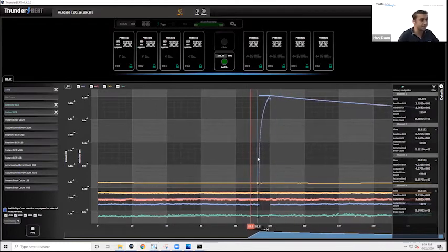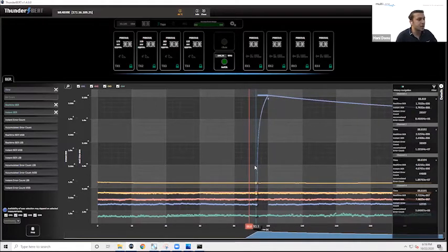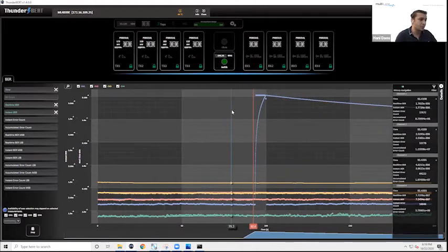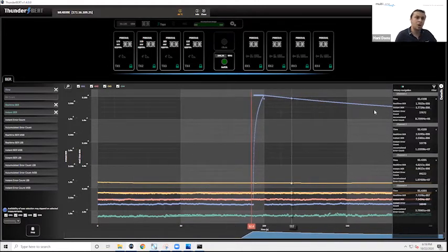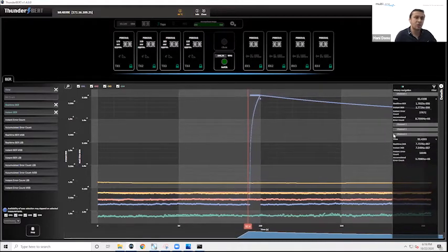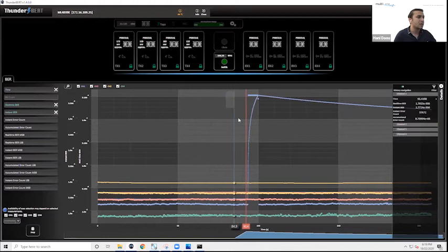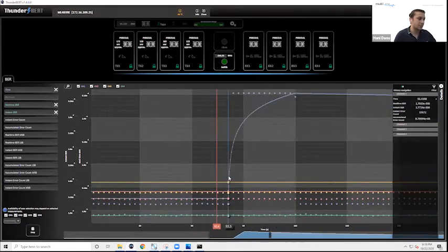So I'm going to jump in here, and I'm going to use my cursor to say, okay, looks like at 92.4 seconds, I'm looking and I'm seeing my bit error rate at channel 1 was still pretty normal. Now let's take a closer look at what happened later. 93.3, okay, as you can see, the real-time, the instant BER is still E minus 6. But if I jump over to 93.6, you'll see, wow, that instant BER is now 4 E minus 3 because of my continuous error injection.